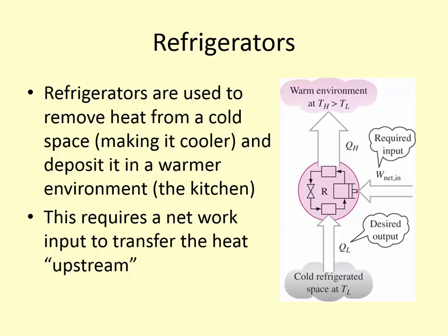So as we look back at the very beginning of the semester, where there was that particular example with a refrigerator in a closed room, and we asked the question, okay, will the room get warmer or colder with the door open to the fridge? You can see again here how we're removing some amount of heat from that cold space, but we're depositing even more heat into the environment. So we can't just assume that it's going to make the entire room cold, because the room now has become the source and the sink, and it doesn't cool down. It actually continues to get hotter, and then the cycle will break down.